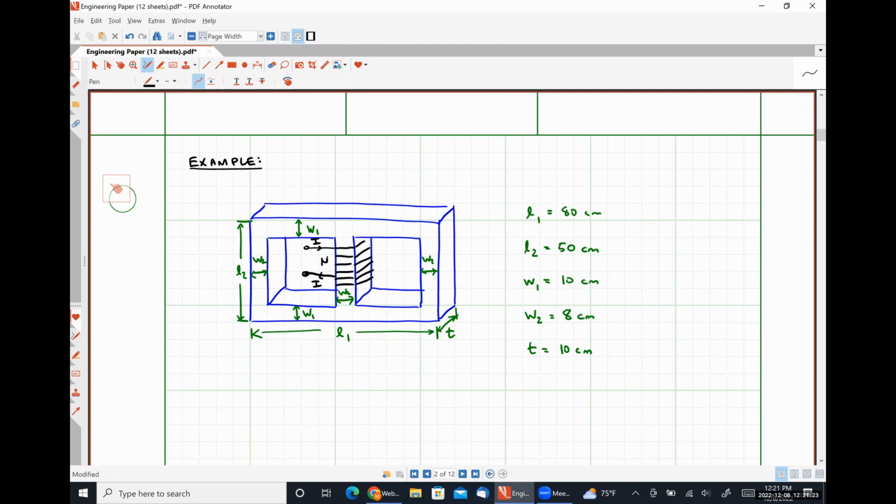Yeah, because the flux will take a different path. And the equivalent reluctance is simply going to be the ratio of the MMF that's driving the flux around our magnetic circuit divided by the amount of flux. So putting the coil in a different place is going to cause a different amount of flux to flow. It's going to look like a different combination of reluctances effectively.